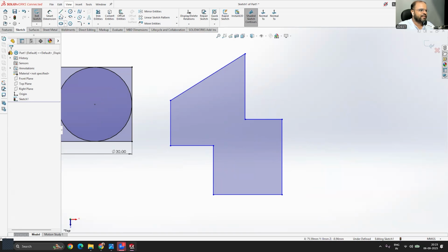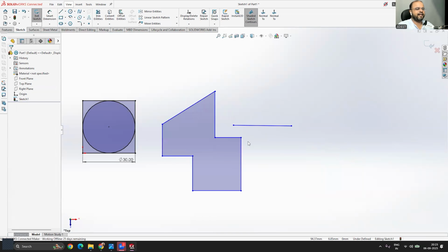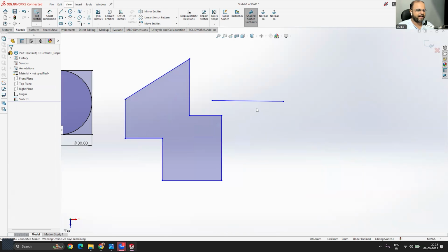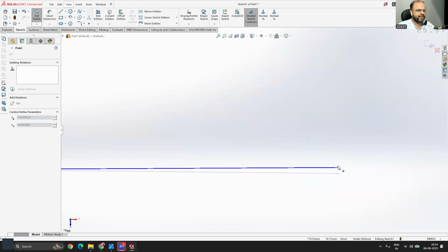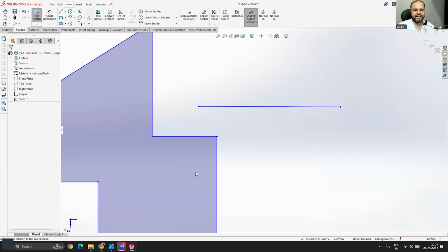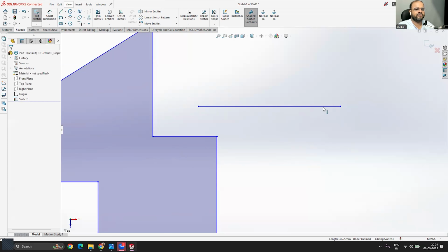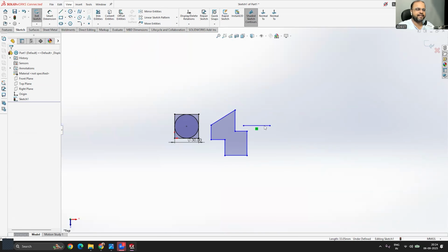Even if, for example, I want to create a horizontal line, but accidentally I created a line like this. If you zoom out from far away, it looks like a horizontal line, right? Even if it is a very small angle, like 1 degree, it will not be possible to identify. This looks like a horizontal line, but this is not a horizontal line. This is a line with a very small angle. In that way, you can have completely wrong geometry. That's why using constraints is important. Whenever you have confusion, simply select the object, apply the necessary constraints, and then you will have a perfect horizontal line. There you can see a perfect horizontal line. And that's why it's important.